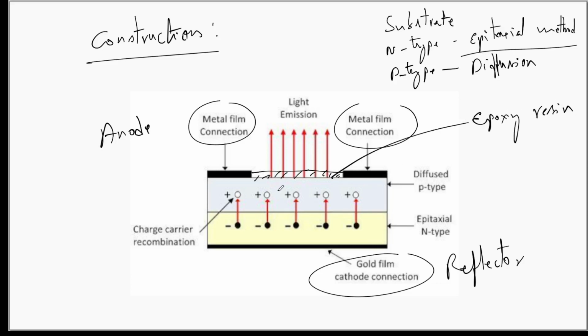because the light emitted from the LED might undergo total internal reflection due to the refractive indices of the P-type material and the surrounding air. The refractive indices of the P-type material and the surrounding air may satisfy total internal reflection for the given wavelength, and the total internal reflection can cause absorption of the photons because the light is reflected back towards the junction.